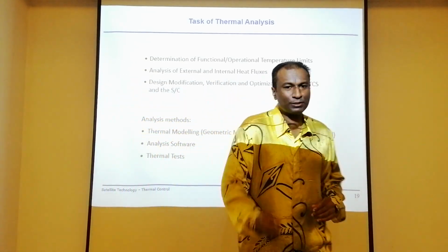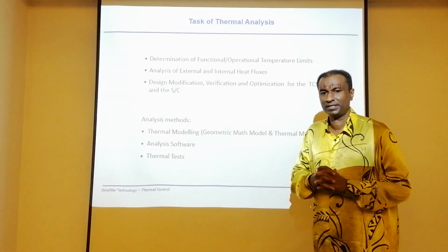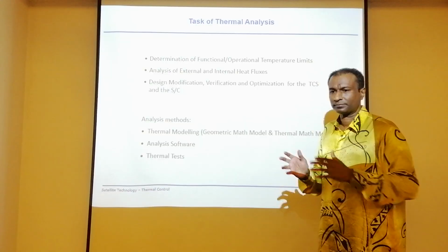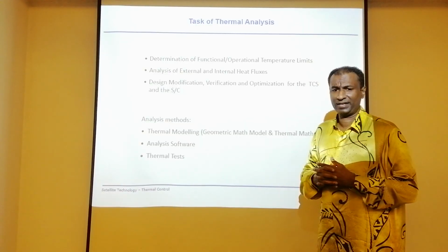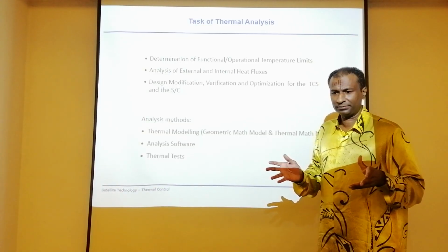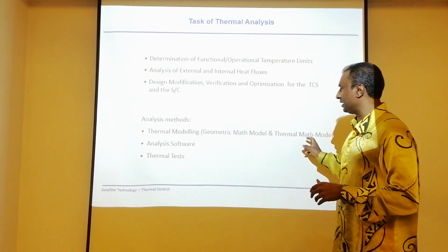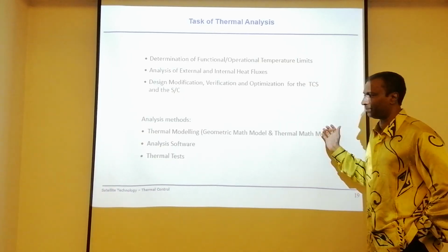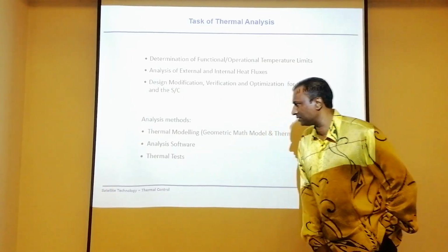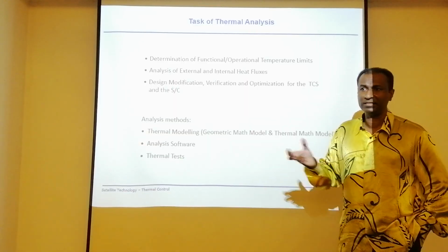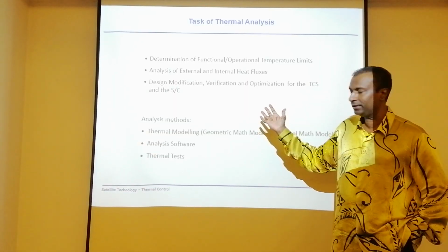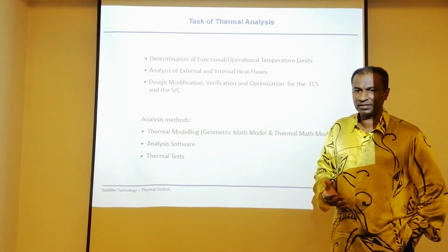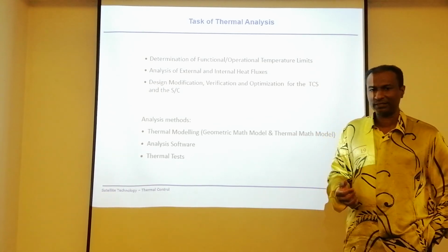We can use the spring method, basically. We can use the parallel and series spring laws, just like you have done in your electrical courses. For the analytical solution, this thermal math model can be applied. Then you have analysis software where you can use finite element to do this approximation. It's quite common. Thermal test, as I said, if you already have the devices designed, then we can look into the thermal test that you want.